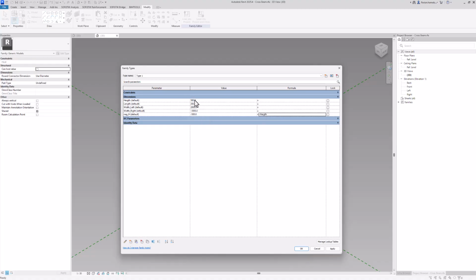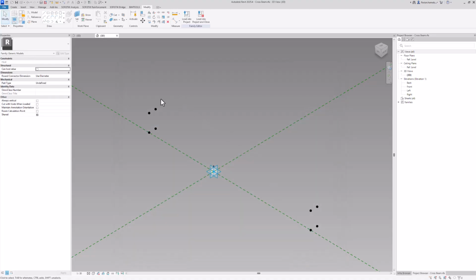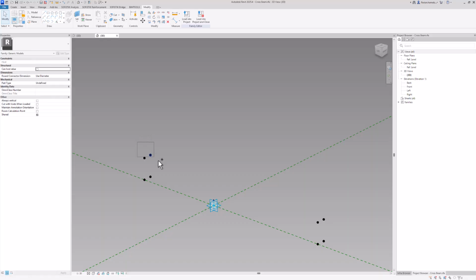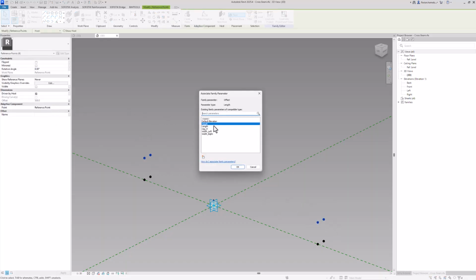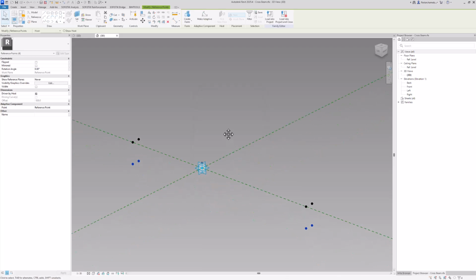And instantly with this input, this parameter will be filled, and formula defined parameters will not be accessible via the cross member functionality. So we don't have to bother much. It will always assign the right parameter here. Now we have to come back to our points, select them, assign them our negative h parameter, and instantly we get the proper cross section.